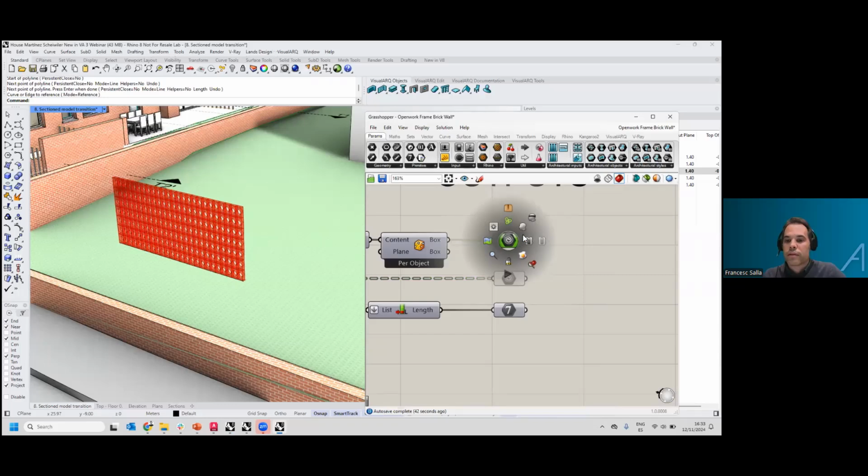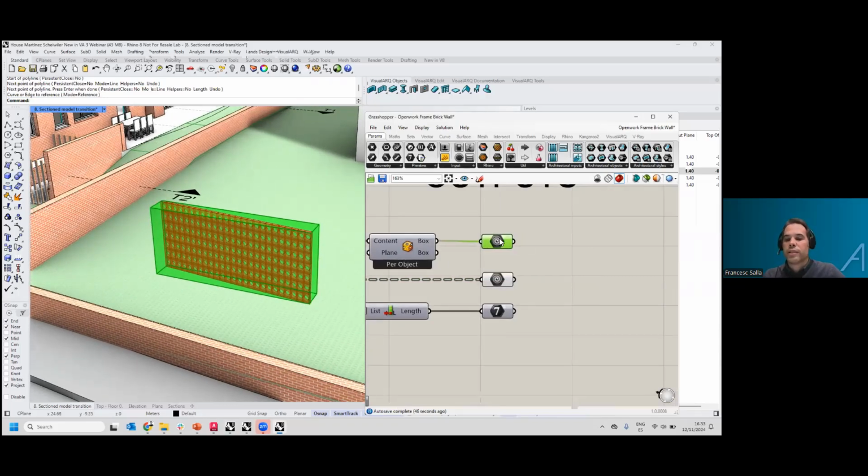I have another one for the volume of this wall. I've called this geometry preview. And this will be the geometry used for the display of this object when I insert it. And that's important because depending on the complexity of the Grasshopper definitions, when you insert a visual object driven by a Grasshopper style, it may be slow, because the definition is being evaluated while it's being inserted. So providing a new volume, an easy one, instead of the real geometry, will make the insertion of this object faster in the model, or also if you drag it or input it in the model. So basically I have created this geometry just for the preview of that object.